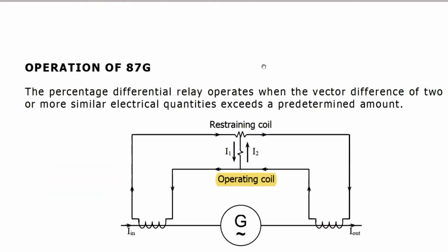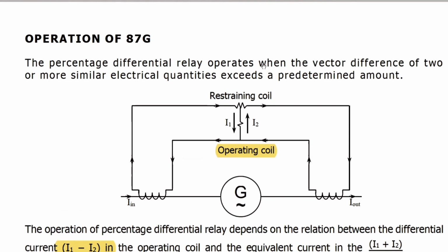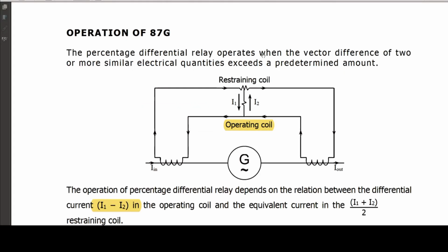And what will it do? Because this is a first class or class A generator protection, at this protection the generator breaker will open. The gas turbine fuel will be cut off, because if only the generator breaker opens and we keep running the gas turbine at full speed, no load, then because this is an internal fault, the fault will grow and the generator damage will increase. So to avoid this increase in generator damage, immediately the gas turbine will trip.